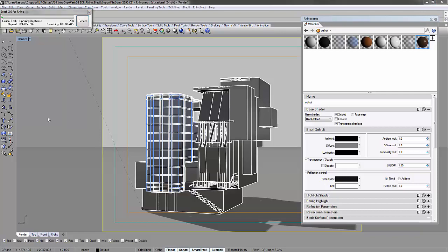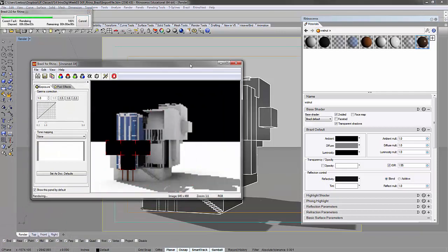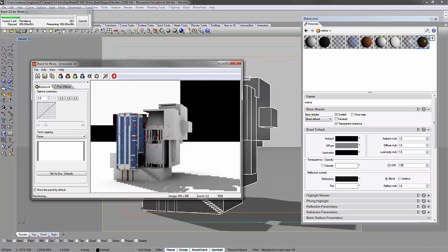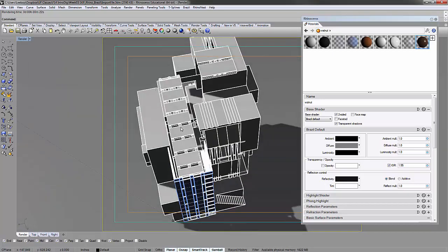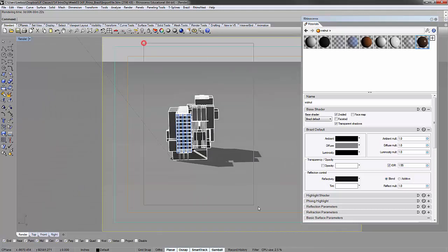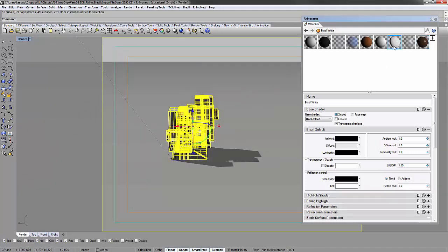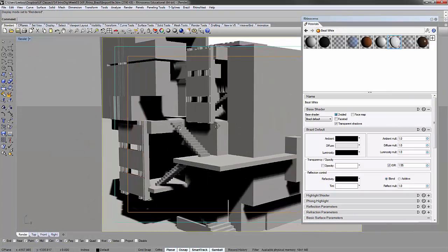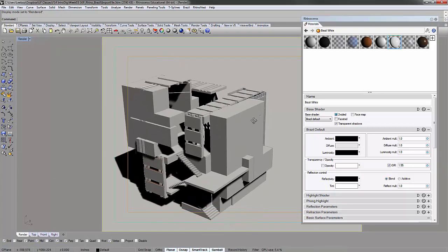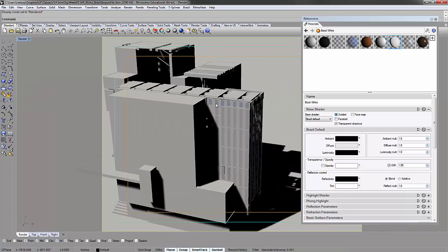If I render this by default, I think you'll see that it's a darker material color. This is probably the default colors that the SketchUp model will come in with. Some of your objects have come in with materials, but it's very inconsistent, to be honest, for the most part. So one thing I'm going to try at first, just to show you, is to select it all and assign the white material to everything, so assign to selection. And if you use the rendered view, you should be able to see what took and what didn't. And you'll see some of the glass is still staying like that.